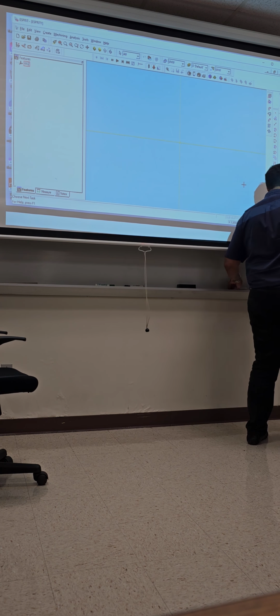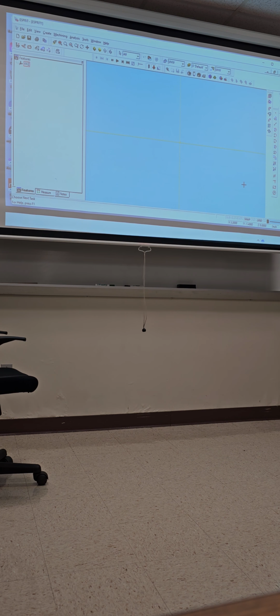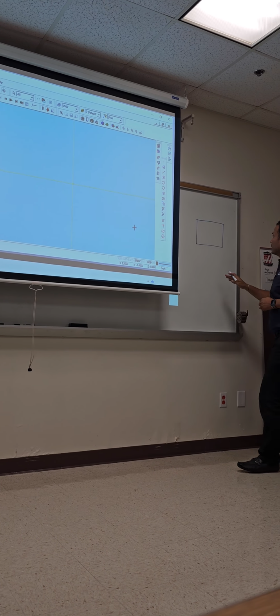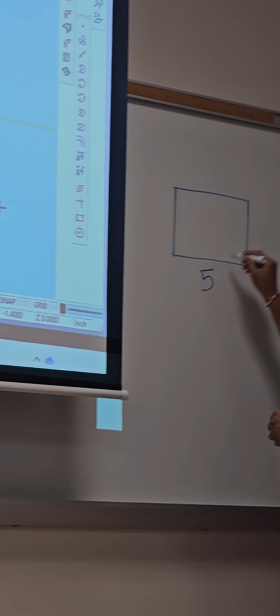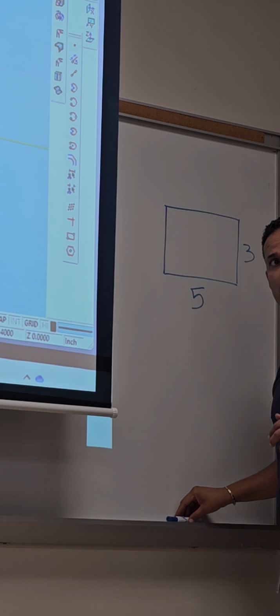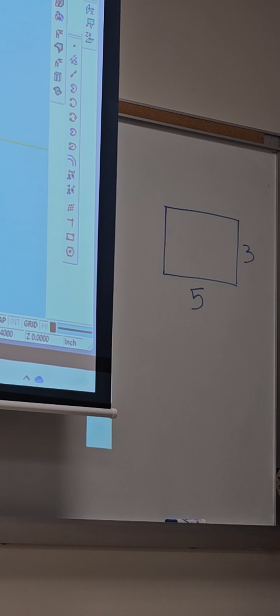Or bar, and that's pretty much similar for the one in the exam. So, not to make it too complicated, I think we've been working with a 5 inch length and 3 inch diameter. Is that correct? Yes. All right. So same thing, we're going to summarize: we're going to face off 0.100, and then turn the OD by 0.100.